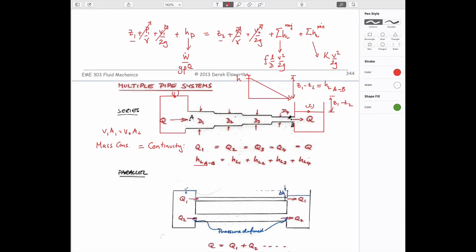So the velocity is increasing as you go downstream, because the areas are decreasing and the flow rates have to be the same. And so you could imagine that if you parsed up this particular sequence of head losses, they would look something like this. They have to go through these final points, upstream and downstream, but the head loss in the downstream part will be larger because the velocity is going to be larger. And if it's turbulent, for instance, and the friction factor is constant, then V squared is actually going to increase faster than D will decrease, right?